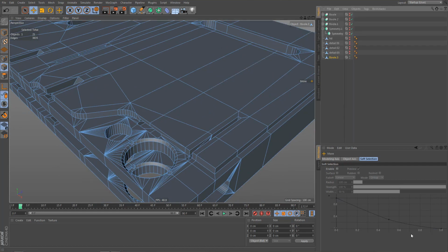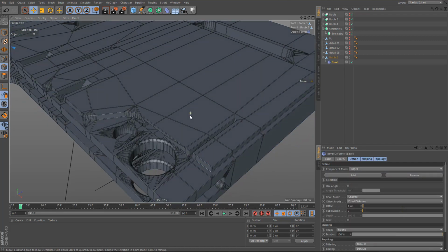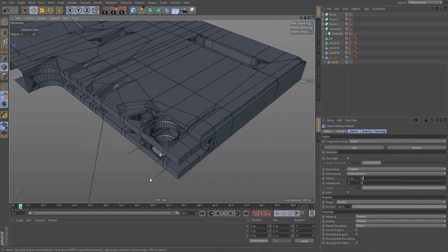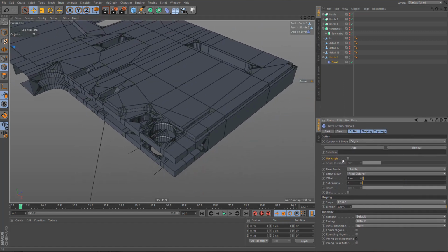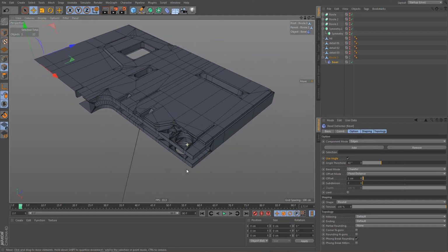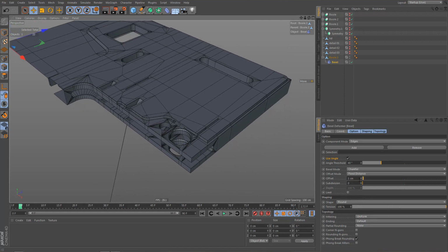And before I continue with the next detail, I'll just test a bevel deformer on this. And you can see we do get a couple of issues. Some polygons are exploded out here. So I'm going to switch on angle, and that gets rid of some of the issues. We could also try and change the mitering to uniform, and that didn't do anything. And one other thing we could do is try and bring the angle down, not the angle, the offset.